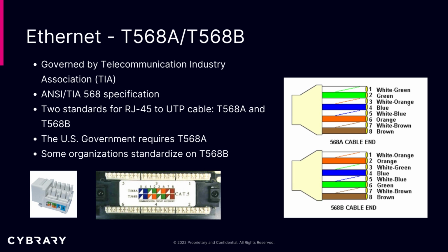In the 568A cable end, you'll see that the pairs start off with the white green wire, then the green, then the white orange, and the blue, white blue, then the solid orange, then white brown, then the solid brown.